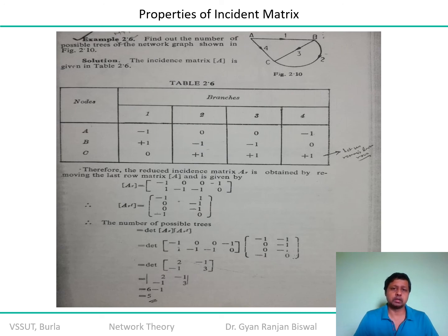So it's always better to approach it mathematically, that is, in this case, the incidence matrix based approach. First of all, you construct the incidence matrix of the given oriented graph, and from there you can work it out. Remember that there is always one node considered as the ground potential, the lower potential terminal, which provides the return path to complete the cycle or the loop of the electrical network.